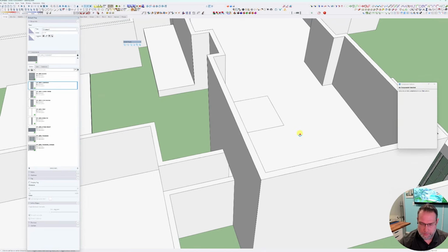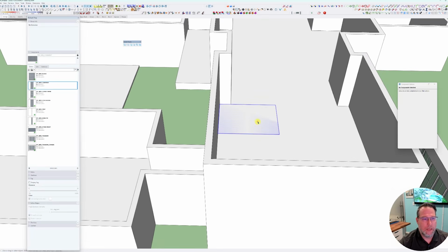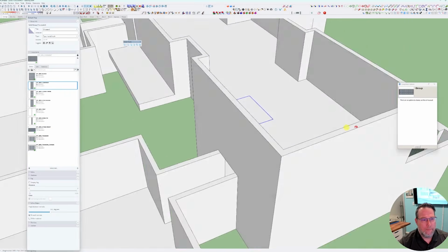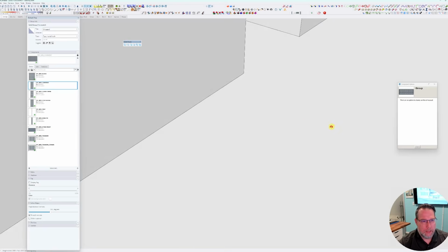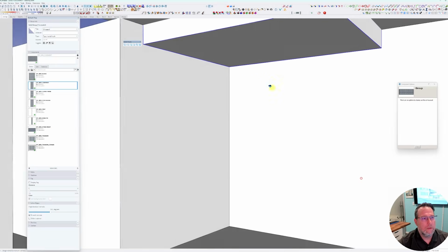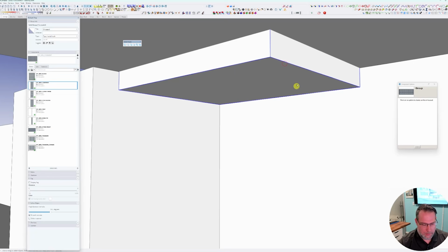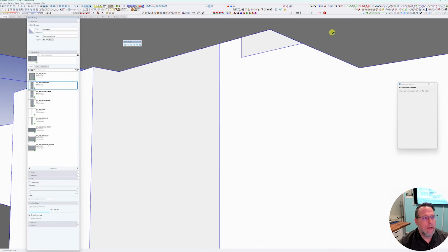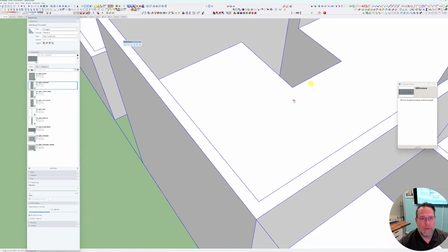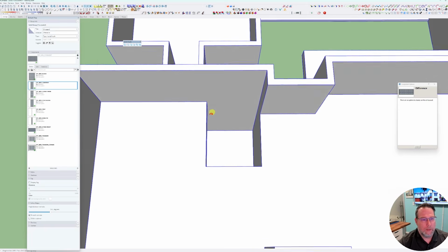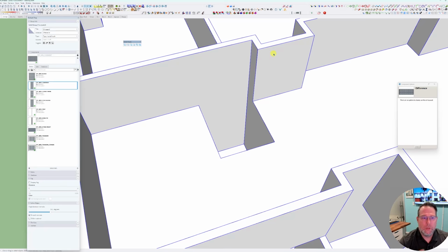opening. I'm just gonna pull this down. Doesn't matter really how far, just as long as I'm not hitting the ground floor. So Control G, and if I go underneath inside of here, you can see this is that box that I just made. And so I'm going to subtract this from my house, and that just now creates a really nice clean stairwell opening.